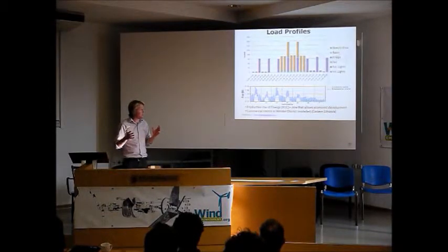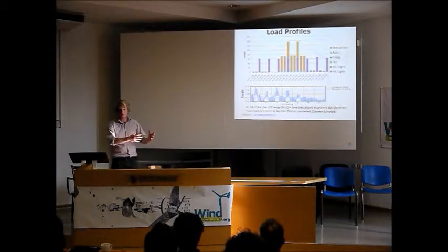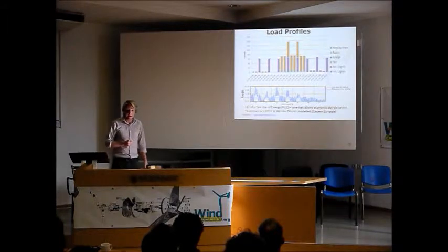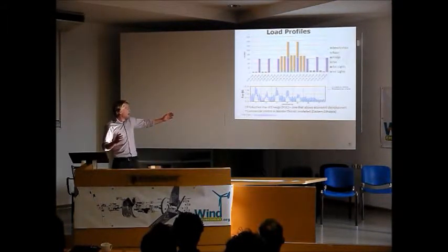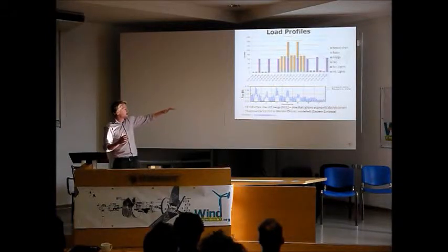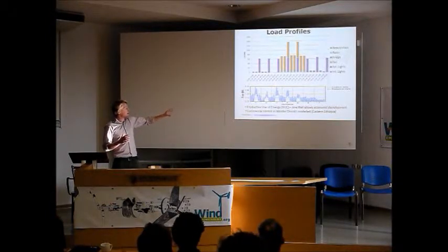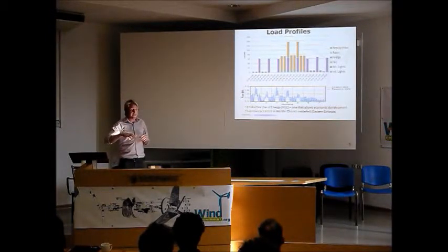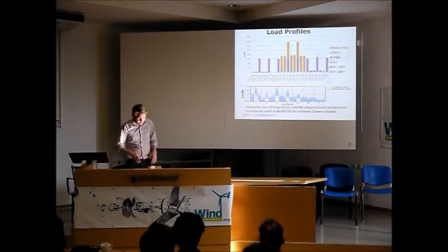So there are quite a few entrepreneurial renewable energy teams doing solar barbershops. This is a commercial centre which has a beauty shop, a razor, a fridge, a fan, and exterior lights. Changing the world one haircut at a time. Homer models the load profiles with some randomised factors so that people aren't switching the loads on at the same time each day. So that's the load profile that you get out at the end.